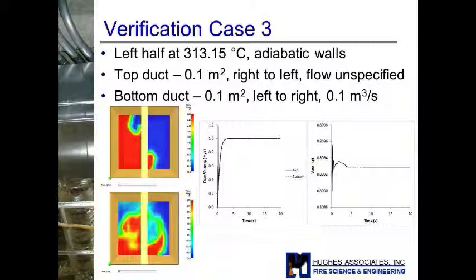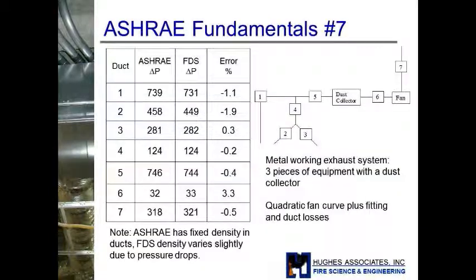You see this is the total mass in the system. So we get a little mass perturbation really early on, and this is mostly a result that this is a very coarse calculation that's being done, so it runs quickly. So there's some numerical error in the mass transport scheme in those first couple of time steps that then steadies out. At a finer resolution, those would decrease.